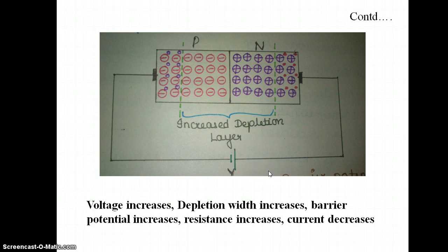As a summary of the reverse bias condition, applied reverse voltage establishes an electric field which acts in the same direction as the field due to the potential barrier. So the resultant field at the junction is strengthened and the barrier height is increased. So the increased potential prevents the flow of the charge carriers across the junction. So a high resistance path is established for the entire circuit and hence the current does not flow. So the potential barrier is increased, the junction offers very high resistance to the current flow. So no current flows in the circuit due to the establishment of the high resistance path.